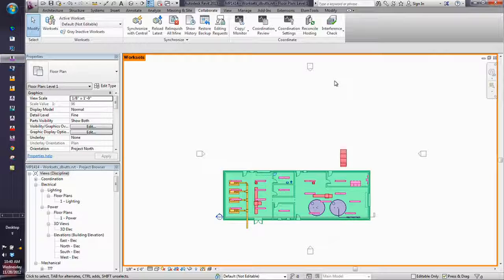And this is a real quick check that you can use to see who actually has got work sets defined, who's actually got them open, and how they're broken up in a project. Have you ever done a print by work set? Anybody ever tried that one out? So if you do your work set by system, you can actually do a printout with different systems color-coded that way. That's another way to approach doing it.